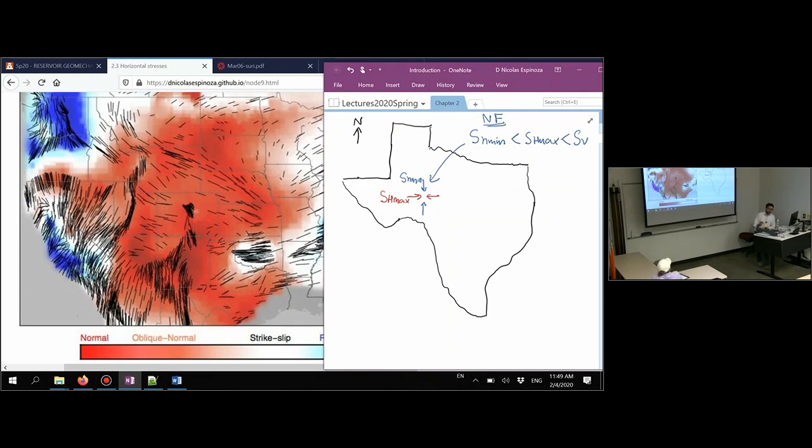And the last thing is that you remember I was telling you that the pressure needed to open a hydraulic fracture in a normal faulting place at least will have to be the minimum horizontal total stress. Well, that's the magnitude of the pressure, but also that fracture is going to open up, pushing against the minimum principal stress. So if this is a fracture over here, let me draw that again, that was not good enough.